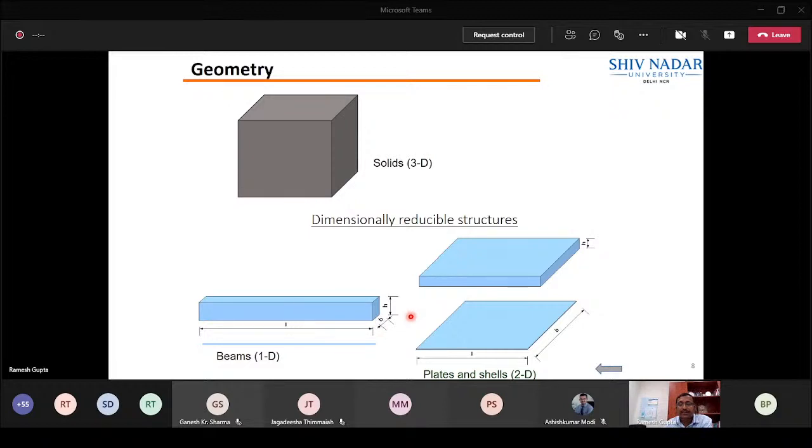That is where we have varieties of elements. Even if you look at plates and shells, people are still working to get a much better representation, especially for composite materials, functionally graded materials, or sandwich structures, multifunctional composite structures. People keep developing elements to fit the theory that can represent your actual 3D structure. Some may use the very fundamental displacement. Somebody may be looking for a simple linear analysis, somebody for geometrically nonlinear or material nonlinear or combined nonlinear, where the physics of the problem or the theory is different from one to another.